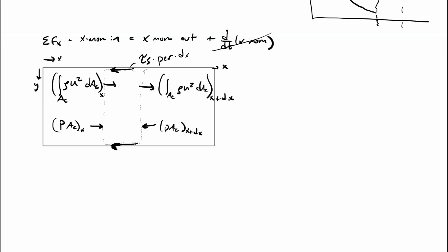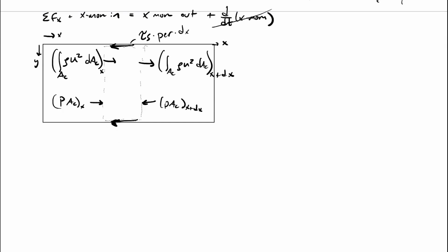And again, the point is we want to come up with an understanding of pressure drop. So let's take this and write it out as an actual expression. First of all, we have pressure to the right in the positive x direction, and pressure to the left in the negative x direction. So that's where you get the signs. Sorry, it's not rho. I did that last time.